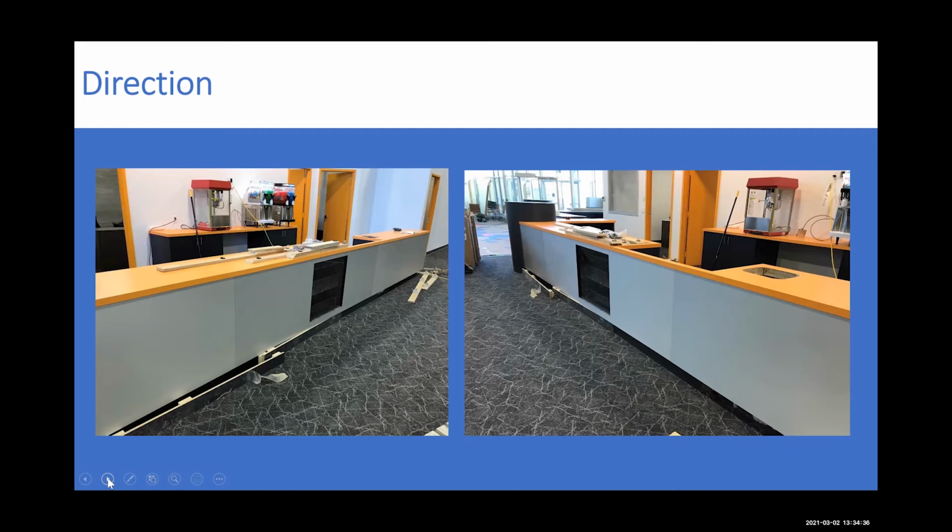This means that during fabrication and during installation, if one of the sheets of laminate is inverted, they will appear to have different colors due to the difference in the light reflectivity. This is a great example here on an install. It can also occur if the fabricator uses an offcut that may be a shoulder-to-shoulder piece, and he puts it together with a head and a toe, it will look like a different color.